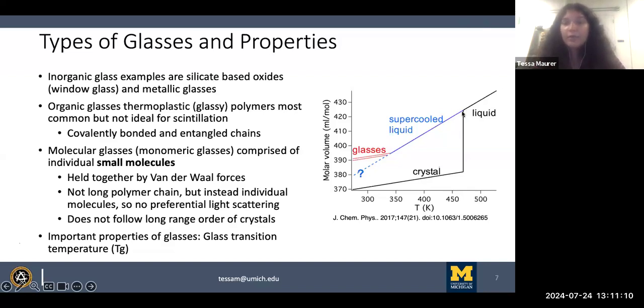So if we cool it so it goes beyond that point, but still cool it gradually, we can get to more of these glasses that you see over here. And the key here is we need to get past where it's going to just full on become a crystal. But we also want to cool it slowly enough so that we can get a higher density glass and a more stable glass. I'll explain a little bit more what I mean by that in the coming slides.